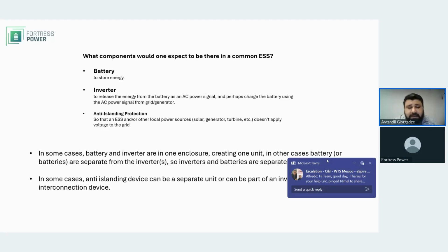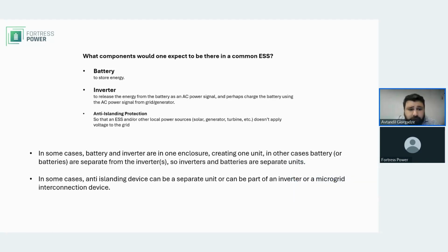Specifically, what I have in mind is when you're using a meter collar, for example. It takes the face of the meter and pushes it out because it also, among other things, acts as a spacer. Really, when we're talking about an anti-islanding device or anti-islanding protection, I want you to think about it as a functionality and not a separate device as such.